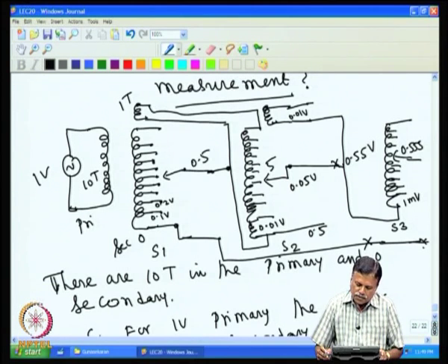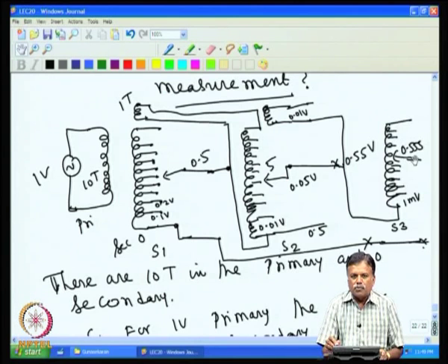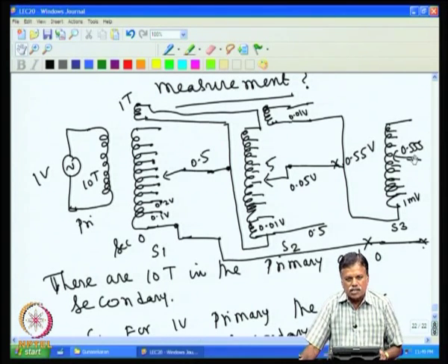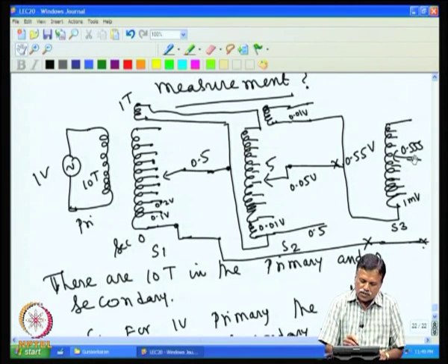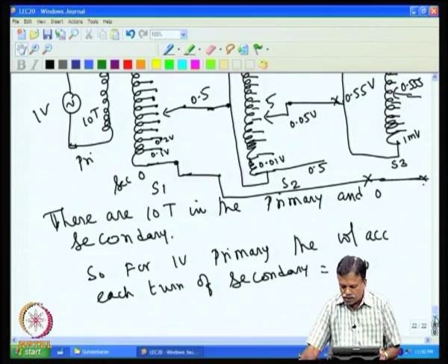So, by this arrangement, by varying the tapping, one can vary the voltage accurately, and there is no need to measure the voltage using a voltmeter, which avoids the measurement error. If you look at this, this is a commercial ratio transformer, and this is how it is made. This is a 3-decade ratio transformer, and for example, if you want to connect the resistance, one can connect from the top and bottom.